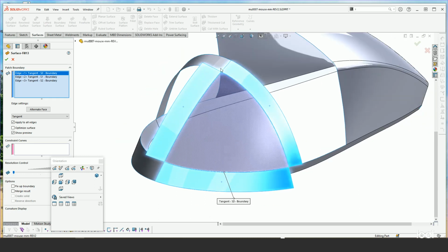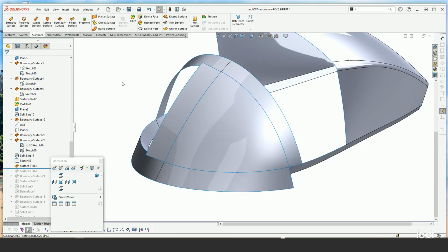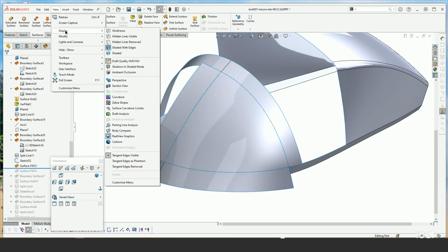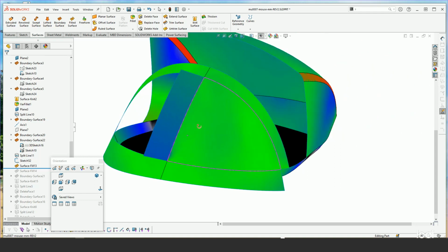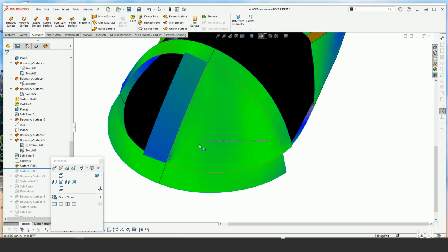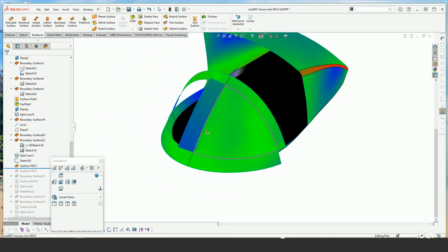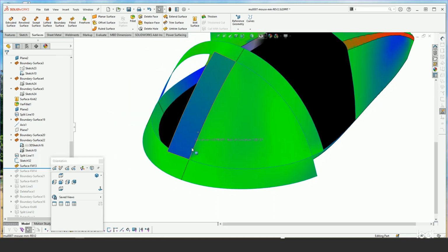So that's what I'm doing here. And if you complete that and then turn on my curvature, you can see that that problem goes away. Now we have a bit of a problem down here again, but it's not that noticeable in the final result. And when we knit to the other side, it kind of goes away.